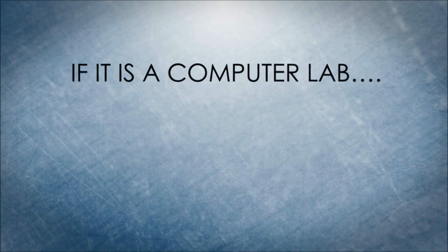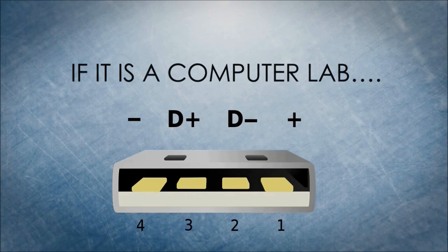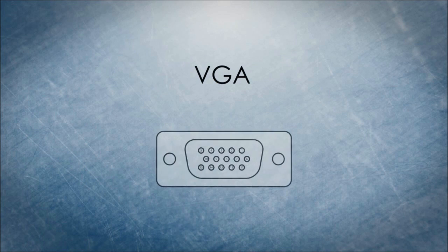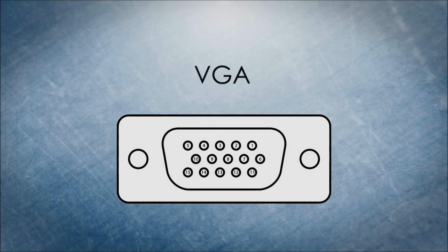If the classroom or lab happens to have computers, another way of detecting presence is by checking which computers are being used. This can be done by tapping connections from the USB port of CPU, which gives 5 volts in on condition. In case of classrooms with projectors, the switching on of projector must be accompanied by the switching off of certain lights. Pins 9 and 5 of the VGA pin, which are +5 and ground respectively, can be tapped for the same.